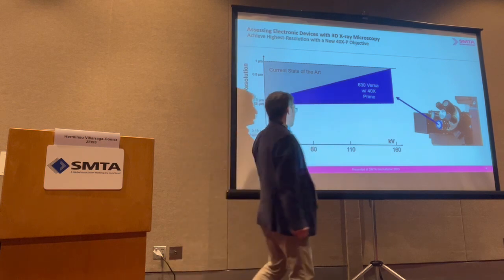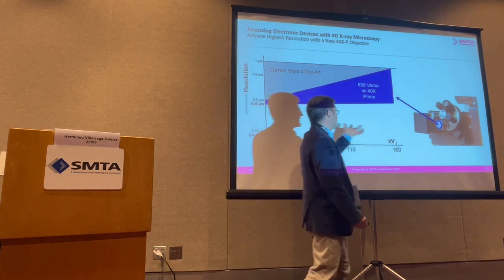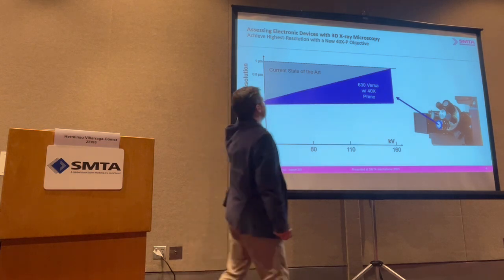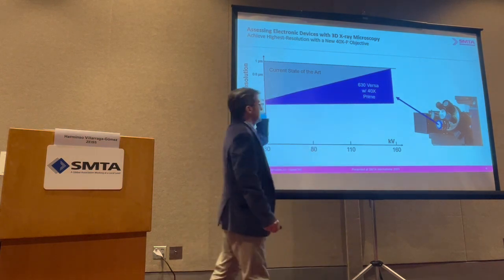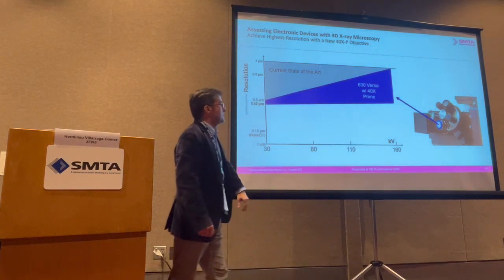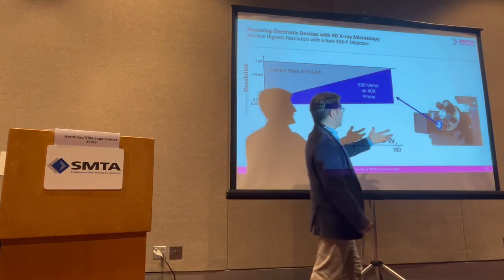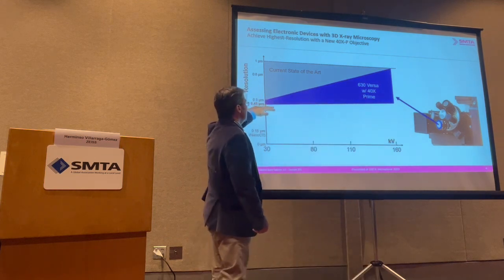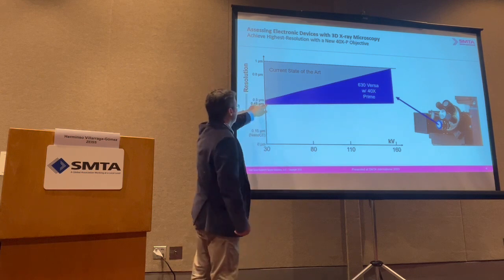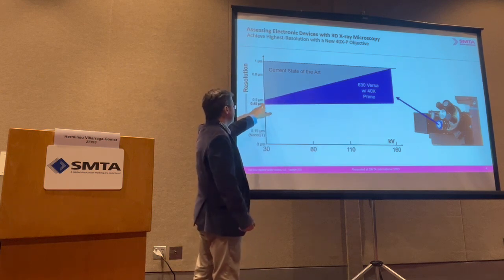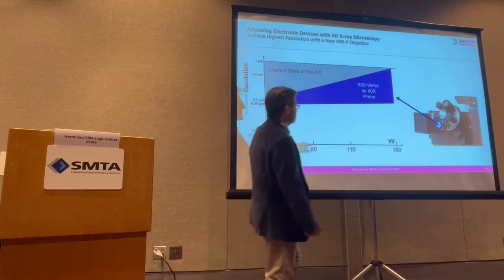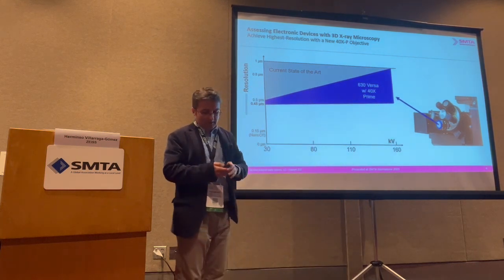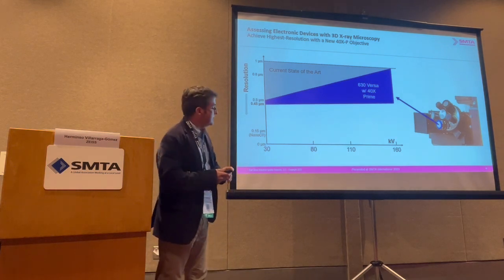Once you start increasing the kV settings of the X-ray source, then those resolution specifications start decreasing, sometimes linearly, depending on the kV that you are using. With new detecting technology, we have been able to keep the resolution down. It still varies quite little from the initial resolution at 30 kV. So you can use 160 kV and still keep the low resolution on those detection capabilities.